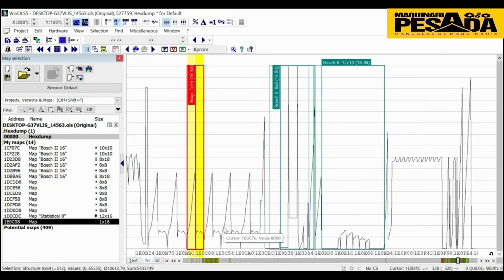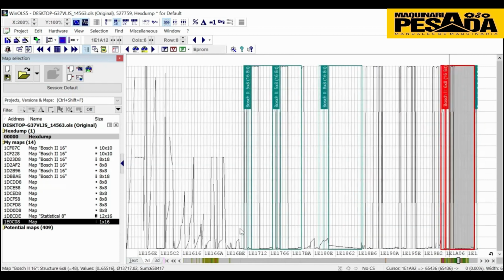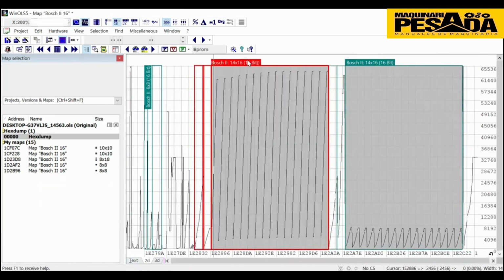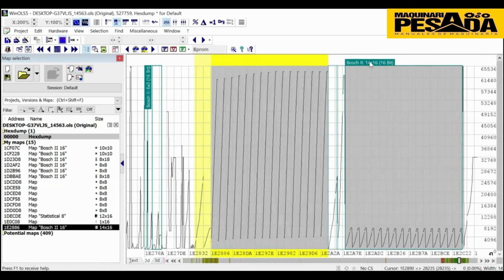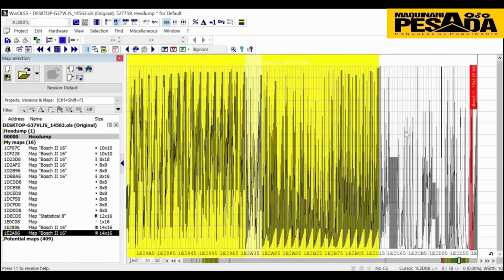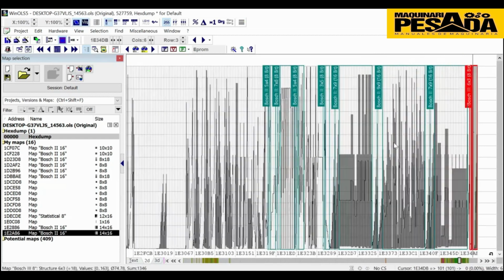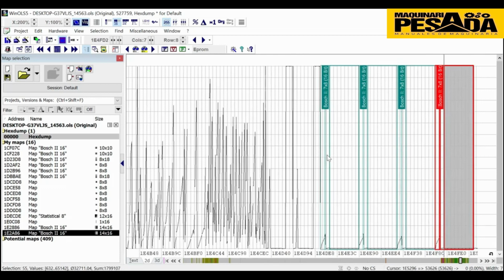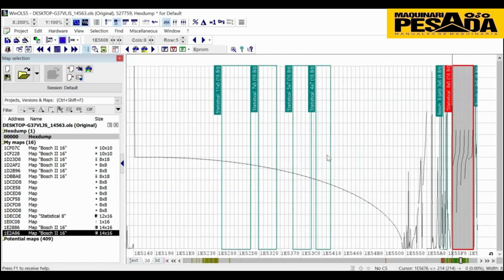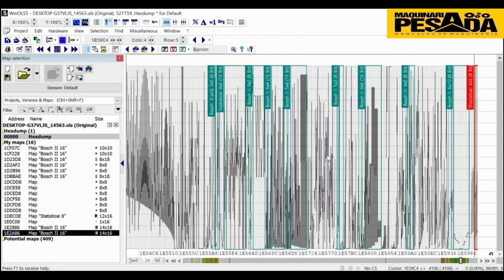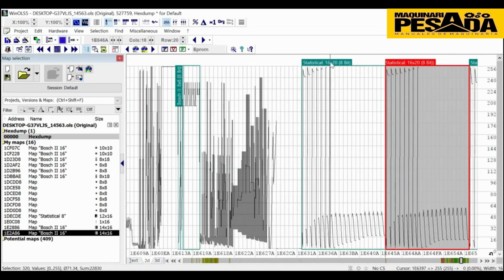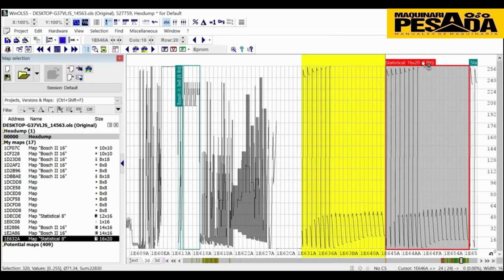These are very important. And next, I'm searching. Yes, here is optimal engine torque. Here is requested engine load, and we are getting closer. These are again injection correction for stage 1. No need to modify or touch them. And I'm looking to find the spark advances. Yes, these maps are spark advance.